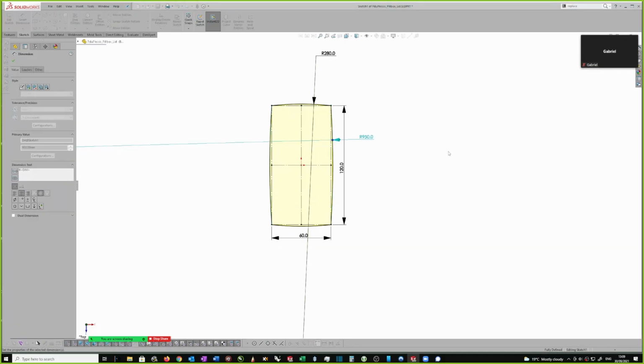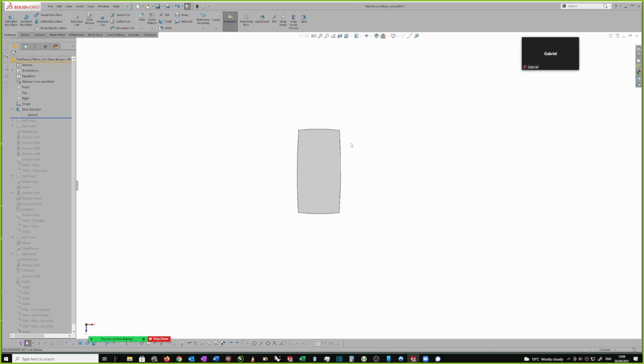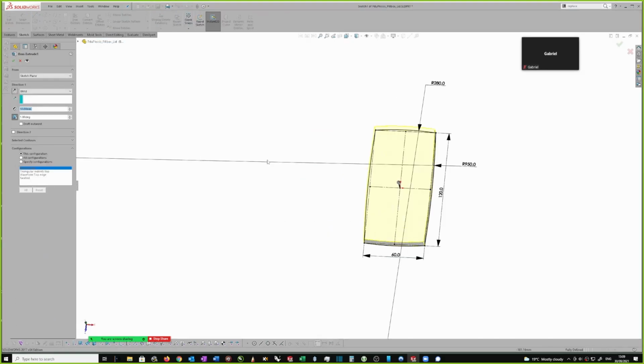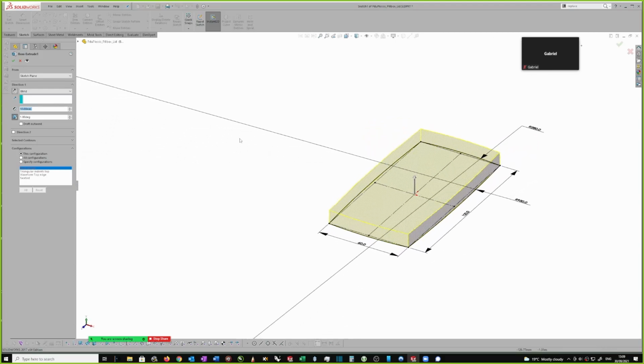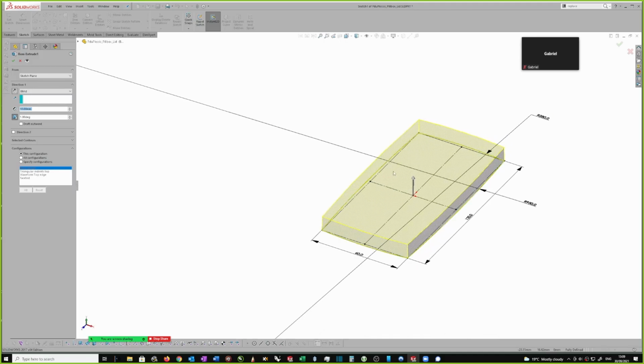Something went amiss there, but I've got those two radii. So it's gone all black. Okay, so that's the basic idea. So let's just go back to this thing here. A reminder that the sequence of modeling is best done as a simple shape without fillets, then the taper.